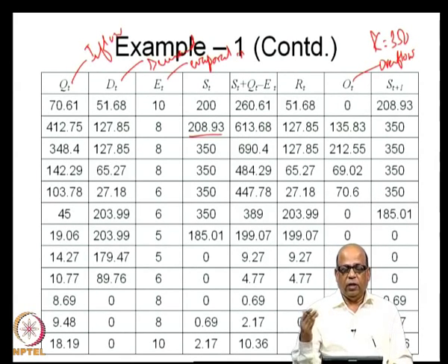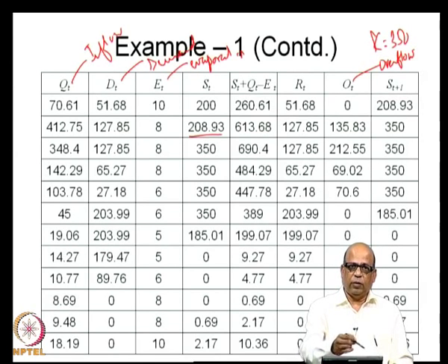So, if you have 30 years of inflow data, the demands may be varying from D1 to D12 only. The same demands will keep on repeating from year to year, but the flows are different, and you apply the standard operation the way I have shown here, simulate the data, and then you will be able to look at how the system performs under standard operation.